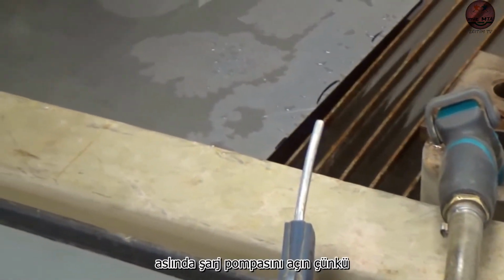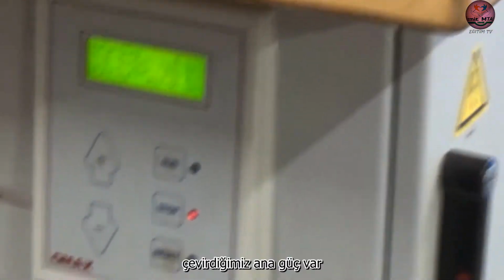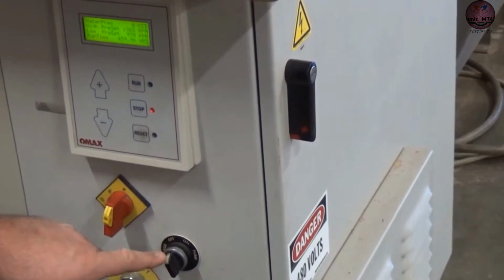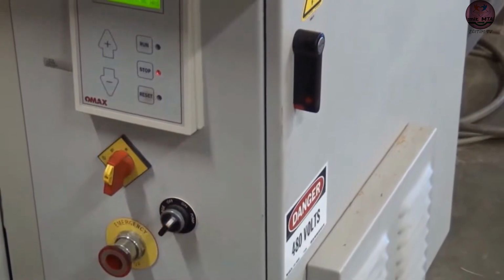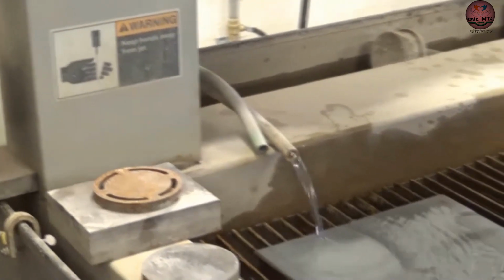And so while I'm waiting for that, I'll actually turn the charge pump on, because I'm ready to cut right now. You don't have to have the piece underwater, but it just makes it a lot quieter and less splash. So over here on the control board, there it is, the main power, which we turn the machine on with. There's an emergency stop switch, and then there's this switch, which says charge pump. Right now it's off. I'm going to turn it on, and you'll hear it start. And then the other clue that your charge pump is running, you're going to see this tube on the right, it's going to be pumping out water.